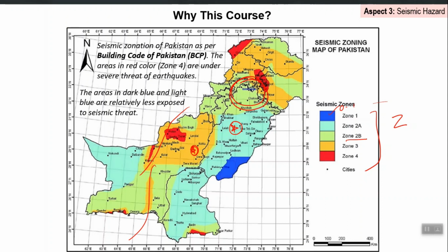And then there are several issues associated with wind loading also. Wind loading is more complex than seismic loading. For example, one of the issues is aerodynamic interference. Imagine that there is a loading which can be modified by the presence of nearby buildings, right. So aerodynamic interference is one of the issues in wind analysis, specifically dynamic analysis for wind. But seismic loading is simpler than wind loading.